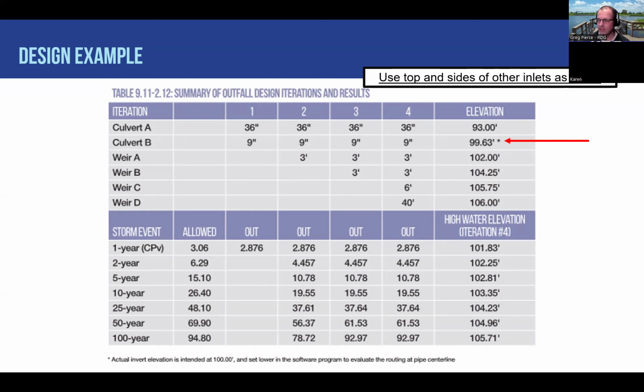And you may have different stages. So we're going to have our primary stage for the 100-year control, and our lower stage to control the 1-year event. But once it gets above the high water of the 1-year storm, we're going to need some other way to get water into the inlet. These could be weirs over the side of the structure, if it doesn't have a top, or it could be an area intake with openings on the side that allow water to get into this outlet pipe. And I'll show some illustrations of that here in a minute.